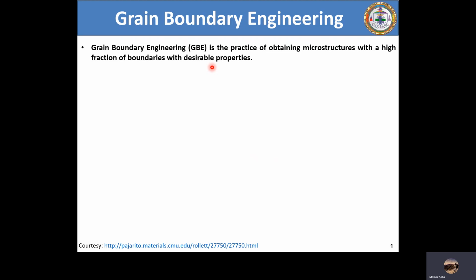We do also have certain local minima, which we describe as the points of special high angle grain boundaries, or the low energy high angle grain boundaries in the cubic materials. Of course, for your level, the simplest of those grain boundaries may also be termed as the CSL boundaries, or the coincident site lattice boundaries.